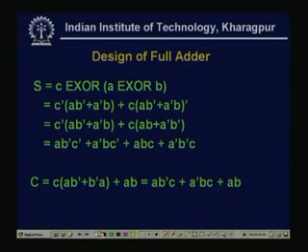See here how we can write, actually this is my AB and this is my BC plus CA. So that also we can write in this way: C times A B dash plus A dash B, and that is also A B dash C plus A dash B C plus AB. In this way also we can write my carry.